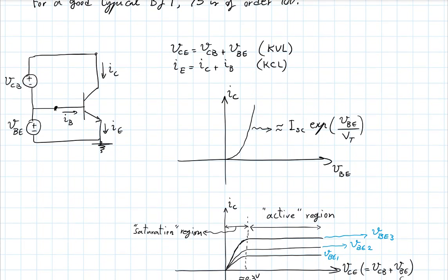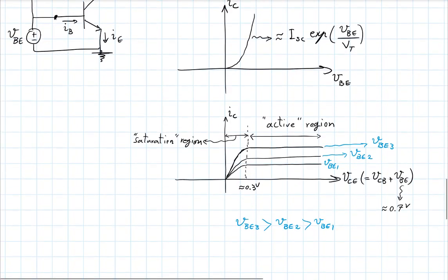One final thing I'd like to mention briefly before we look at examples is this. I've been saying how the base emitter junction is a diode, as indicated by that arrow. Actually, the collector base portion is also a diode, because the structure of the device looks like this.